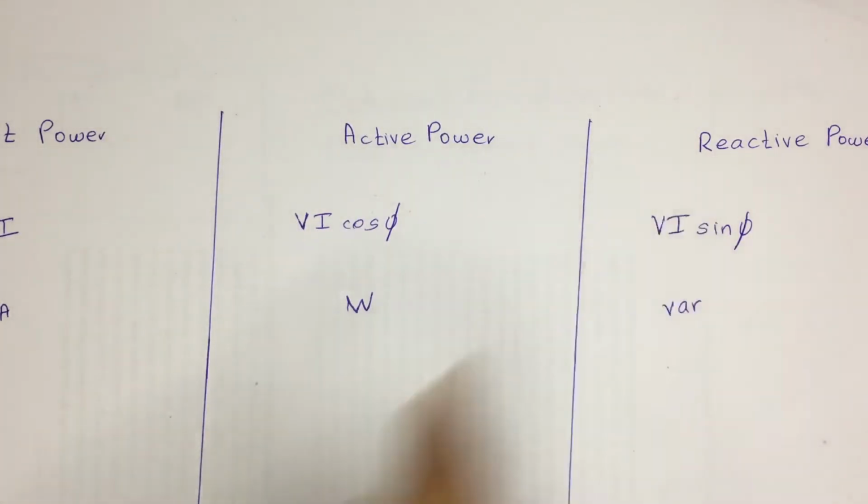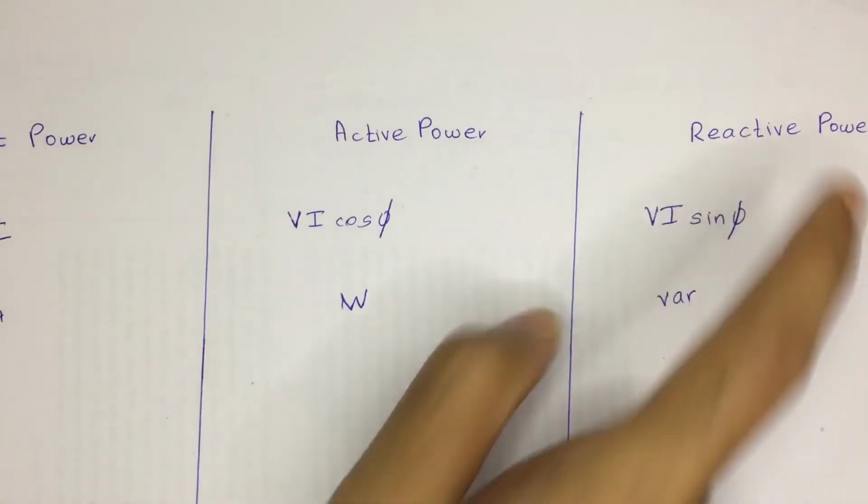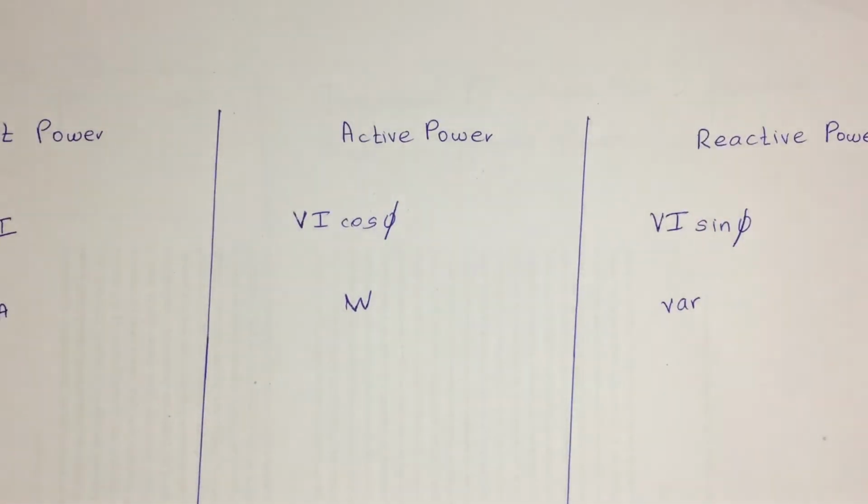The reactive power simply means the power that, in an oscillation of the sinusoidal waveform, when the current passes through the capacitor or inductor, is stored and then returned. The storing power is known as the reactive power, which means it is not wasted, or we are not going to use it. It returns that power when the current changes direction.